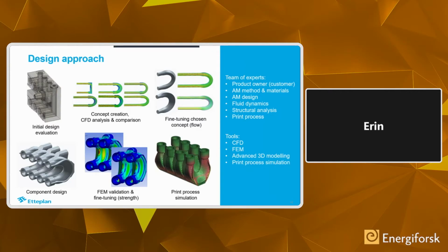And here we used finite element analyses to analyze the strength and the performance of this new design, and to go throughout the part and optimize the wall thickness to be as thin as possible where the loads were low, but then to be thick enough in other regions, and to also determine locations and dimensions of needed rib structures that were added during the final fine tuning of the design.